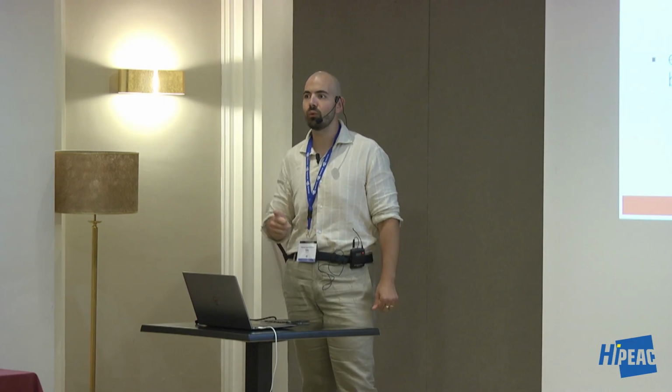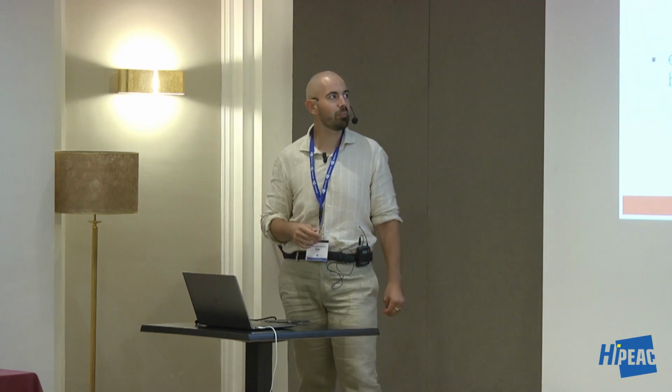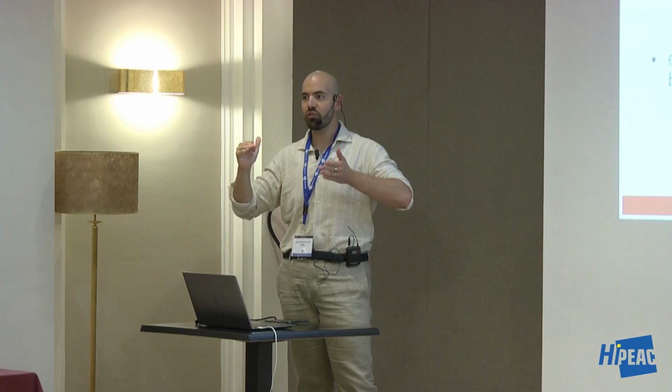Okay, so we saw custom hardware, we saw custom, let's say, application. Are there other ways to do energy efficiency? Power gating and clock gating. Okay, so he says power gating and clock gating, which means switching off what you are not using. That will reduce the power, so you keep the computation the same, but you consume less power, so the product is more energy efficient.